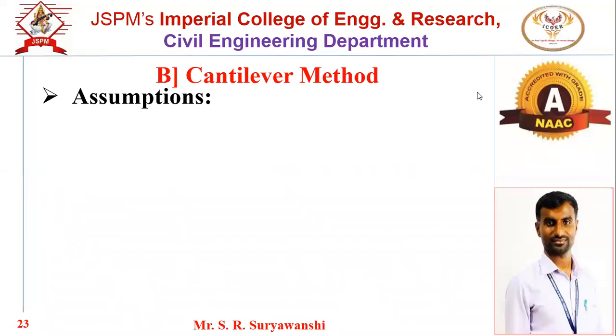First assumption. Sheetal. Points of inflection are located at mid height of each column. Yes, very good. Point of inflection is located at mid height of each column, meaning the bending moment will be 0 at mid height of each column. Good.